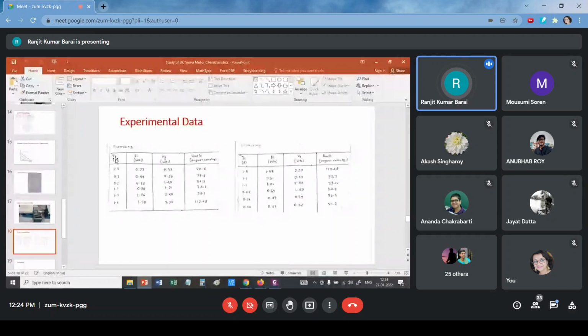This experiment should be performed continuously. You cannot give a break. When the motor starts rotating, and from maximum, because of the heating, etc., and saturation consideration, that is the maximum current, and then you go on decreasing it gradually, and note down the speed as well as the armature voltage.